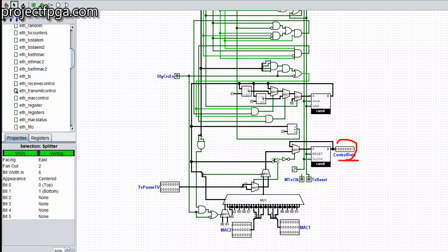So whenever it is 1 here, it has already taken 2 nibbles. So those 2 nibbles will join together. Assuming this NOT gate is not here, whenever it is 0, when this multiplexer is going to come on, it's going to have only 1 nibble. So it delays it by using this NOT gate. Whenever it's 1, it delays. Then the next time there are already 2 nibbles. So that is how we get this control data.